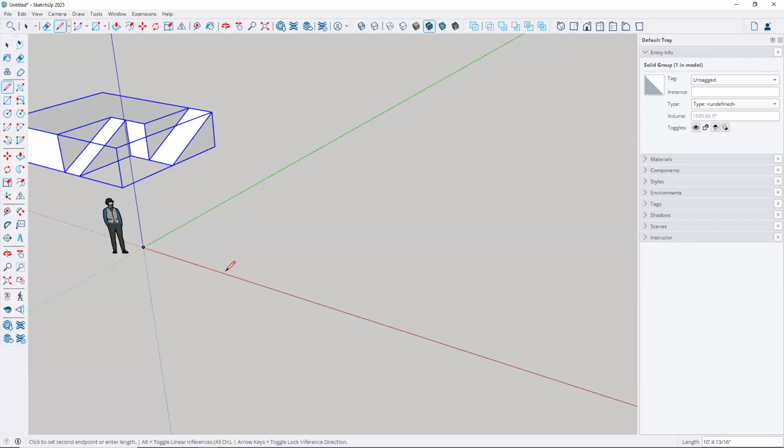And then I want to constrain to red. And as you begin to use the program, just use the right arrow key. Get comfortable with that. So constrain to the red axis. And then you see that down in the bottom, it's giving a length. And right now it says approximately 12 feet, 5 3/8. So let's move the cursor a little bit further, and it's around 18 feet.